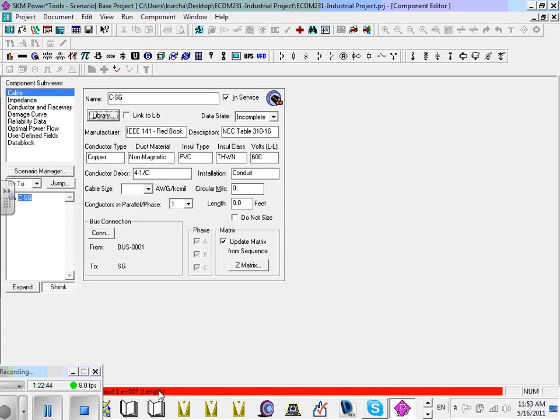Okay, don't worry about the sign that you did. Did you guys load this cable? Yes. Now, do me a favor. We're going to go to the size. It's a 4,000 amp switchgear, so I'm going to run 500. You guys have to fill it. Here's where I'm going to run it. Can you guys see the size? I'm going to go 500.